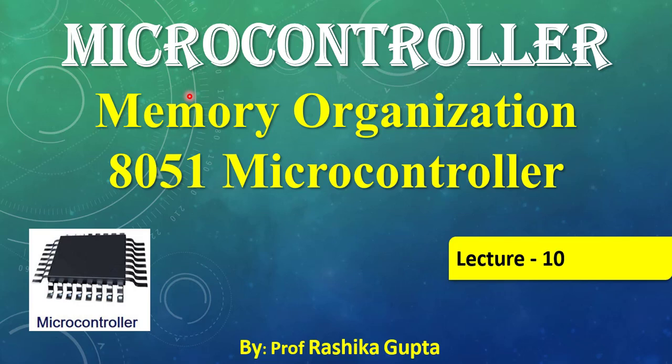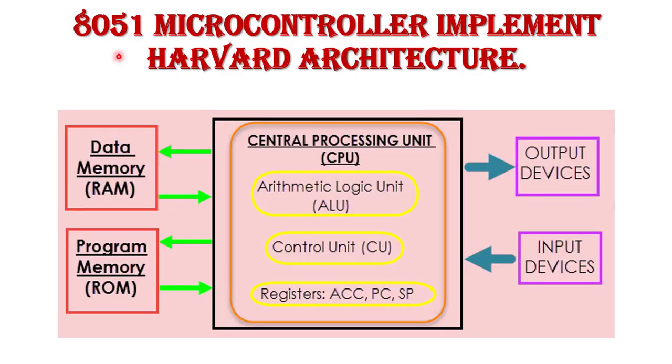In this video, I will explain the memory organization of the 8051 microcontroller. This is lecture number 10 of the microcontroller series. Before I discuss the memory organization of the 8051 microcontroller, we know that it is based on Harvard memory architecture. In Harvard memory architecture, we use separate memory to store data and to store program.